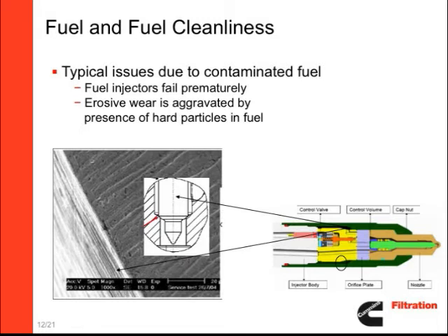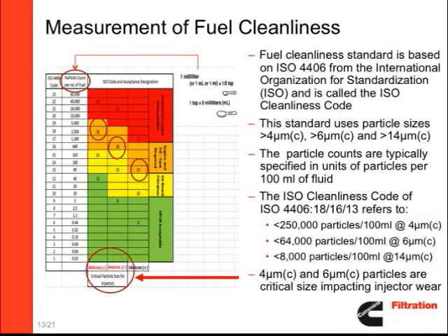The illustration below shows a standard fuel injector. The magnified slide to the left shows erosive wear on the outer edges of the control valve, where hard particles in the fuel have caused damage. So, how is the cleanliness of fuel measured?